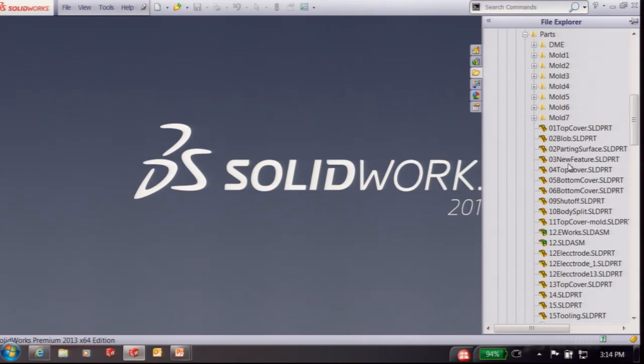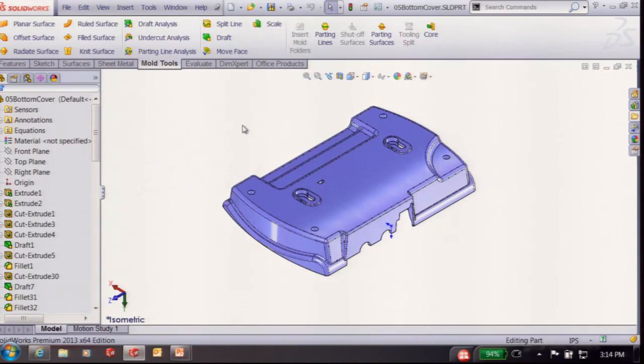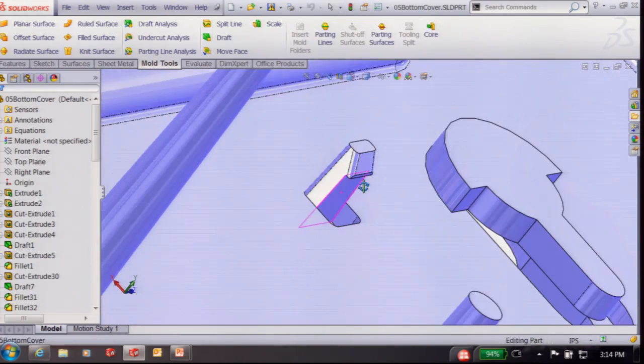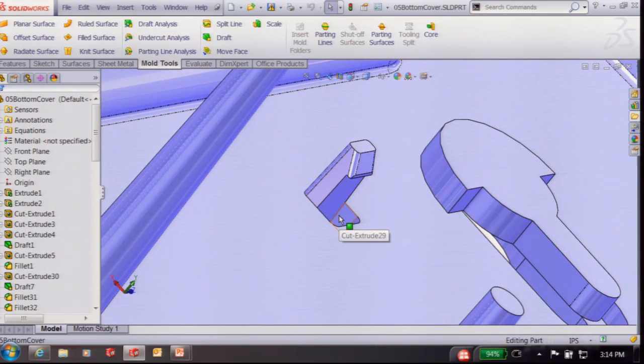And so for these parts, let's see, where's that at? Right here. I got a couple of ways I did this part, just as an example. This first one, you can see the geometry is such that we have this little clip, and it has sort of an undercut, so we build up material to make that undercut that comes up from the other side. Of course, there's an angle in there, so you're not grinding on your faces when you're opening and closing your mold.